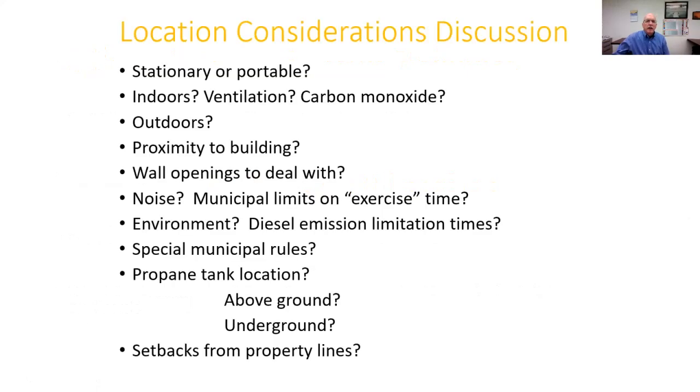All right, part 1, deciding on a location to put this 22 kW or 15 kW generator. Do you want to have a stationary one, or do you want to have a portable one that you roll out of your garage or your shed? Do you want to put it indoors, outdoors? What about ventilation, carbon monoxide? Well, these units don't lend themselves to indoor installation.